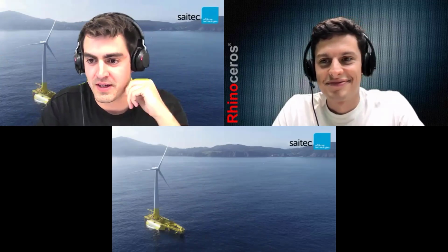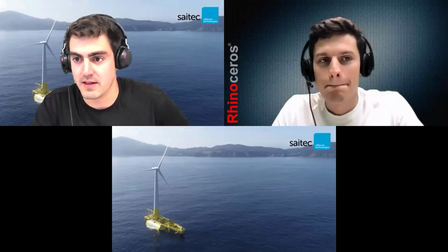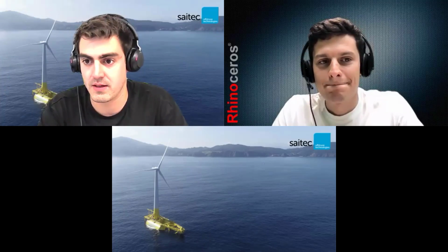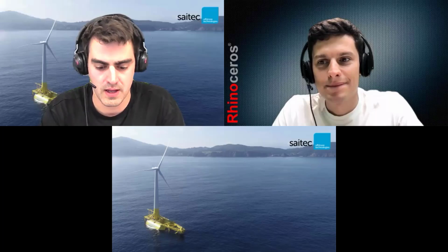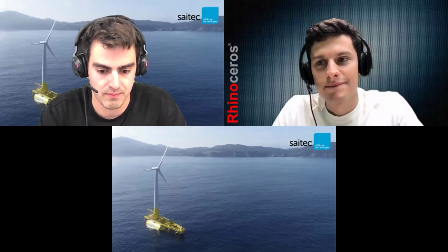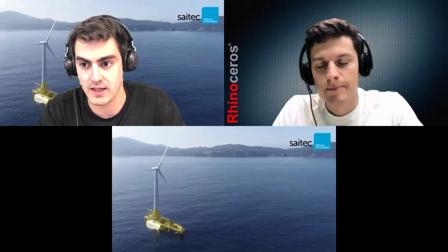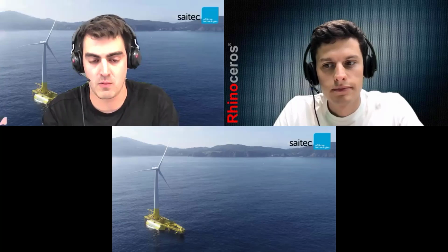Well, sorry about that, the screen just went down. Okay, so what I was saying is that we have a Python script that is automatized for taking the outputs that we have from the RhinoScript and the mass model, and it goes to Genie to create the mesh, and then it's imported directly to HydroD, and then we receive a text file with the results of the stability and the frequency domain calculations.